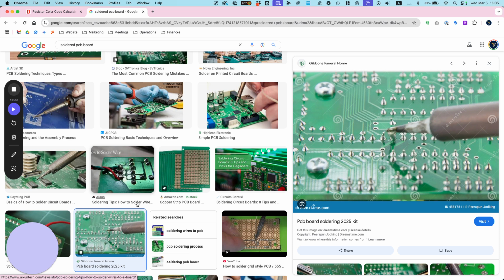All right. As conclusion, current is the movement of electrons from atom to atom. As you saw here, in order to measure current, you need to be in the loop. You have to be part of the circuit. Voltage, on the other hand, is the potential. It's like the pressure difference. So you can measure pressure in a pipe even if the spigot's not on, right? Or when the spigot's on, you can still measure the pressure. So you can go across just to measure it. It doesn't have to be a live circuit.